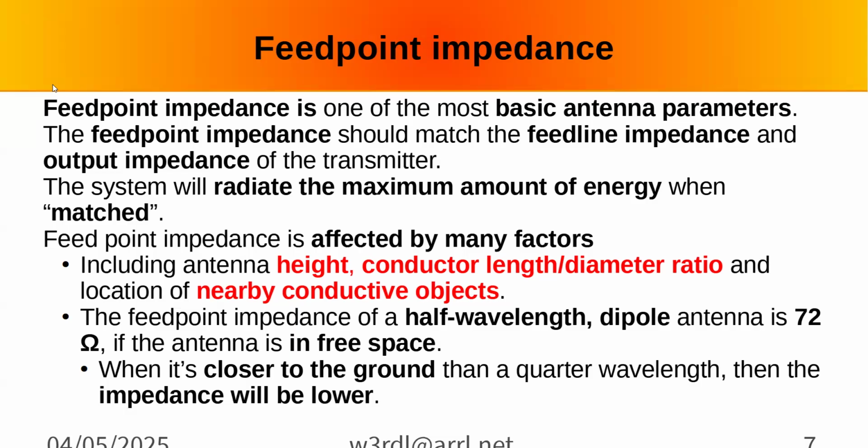And normally you're going to use a 50 ohm feed line because your transmitter is, unless you really have something weird, going to be 50 ohms. Or you're driving it with twin lead or ladder line, which is higher impedance. Normally you don't have that on the back of a transmitter, but antenna tuners, particularly the older ones, sometimes have outputs for ladder line and random wire.